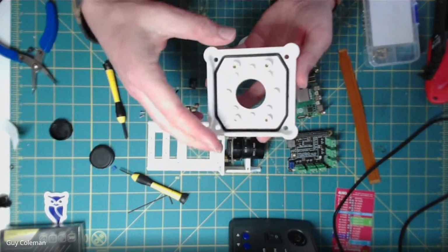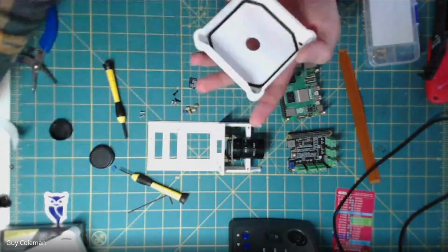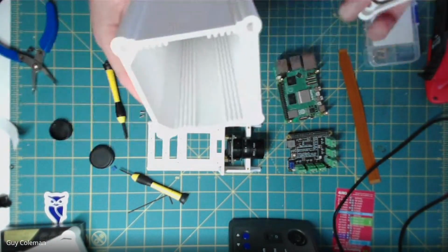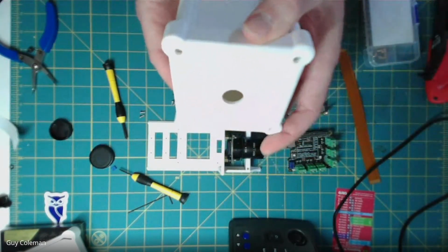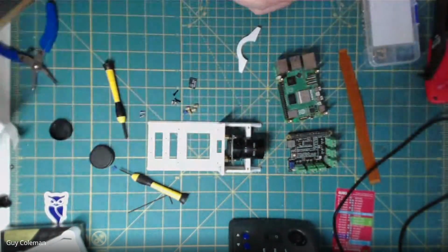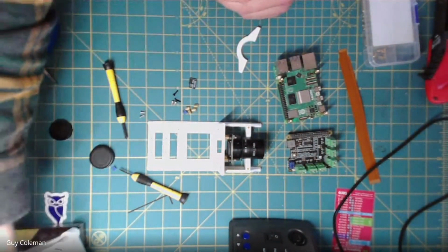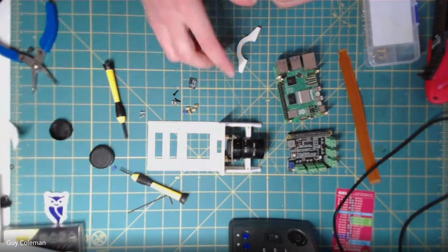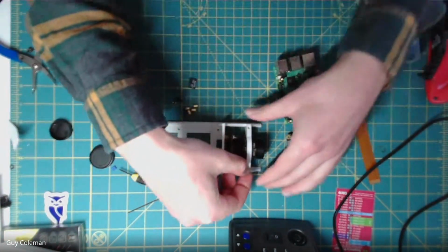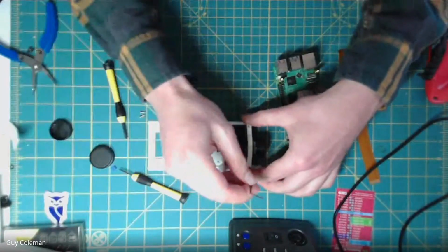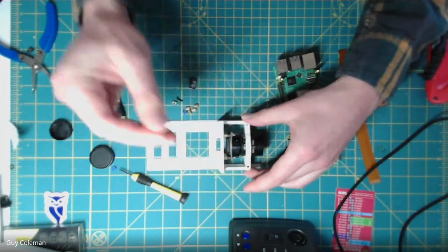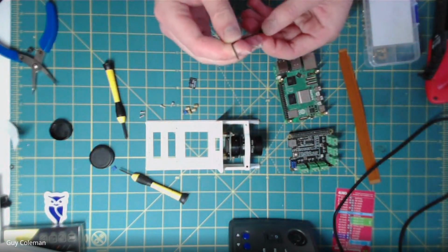You can use this for the camera module 3 mount, and you also need them, these are M4, to tighten down each of these back fittings onto the enclosure. So you can see this is what it looks like without them, but you'll need to add them if you're printing it yourself to make sure it's locked in place. So to put that on, we use an M2 hex screw, and just tighten it down. You don't have to tighten it down too much, otherwise you won't be able to focus it later.